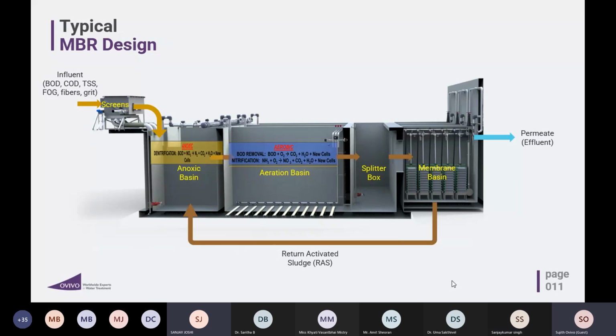What generally we do is, it's just out of topic. While commissioning the MBR system, we try to maintain an MLSS of minimum 3 to 4,000 MLSS, right, to commission the system. Otherwise, your membrane will get fouled. So we make sure first this biology is working fine. Thereafter, we pass the water to the membrane basin.